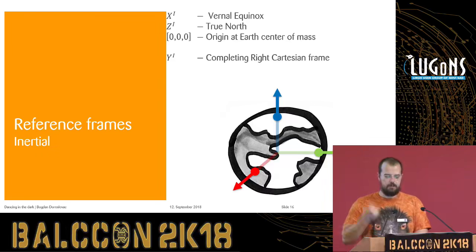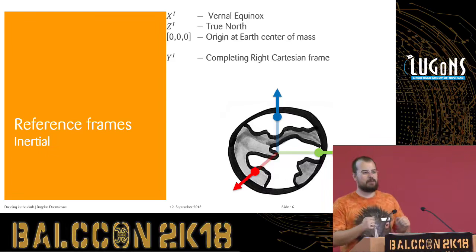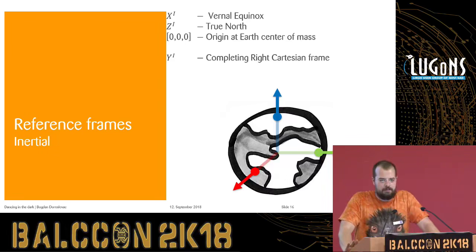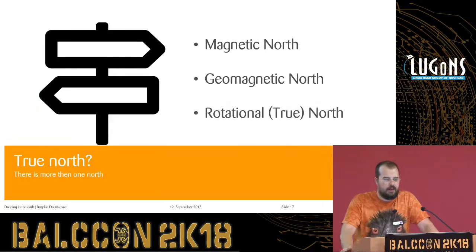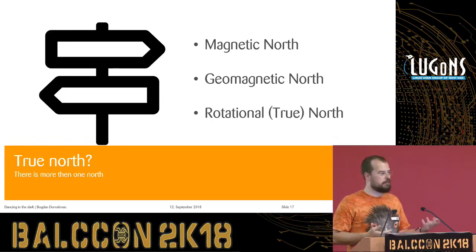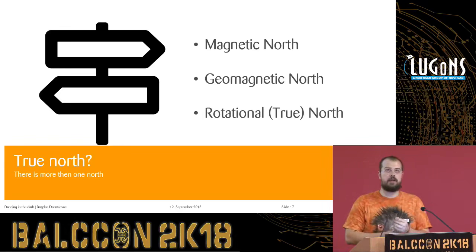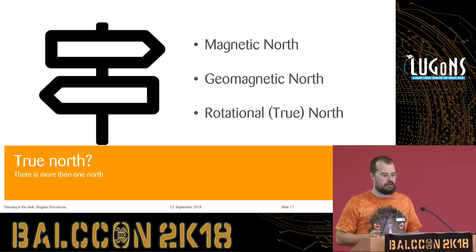Now, you'll notice here one interesting aspect again. North. There's a concept of true north. Why true north? There are actually many norths to begin with. What you see when you get your compass out, it's a magnetic north, which is highly imprecise if you're getting close to the pole, which, by the way, also not only is imprecise, is shifting over time. So a lot of things like ADIRUs have to compensate with magnetic variation or Magvar tables, and so on.